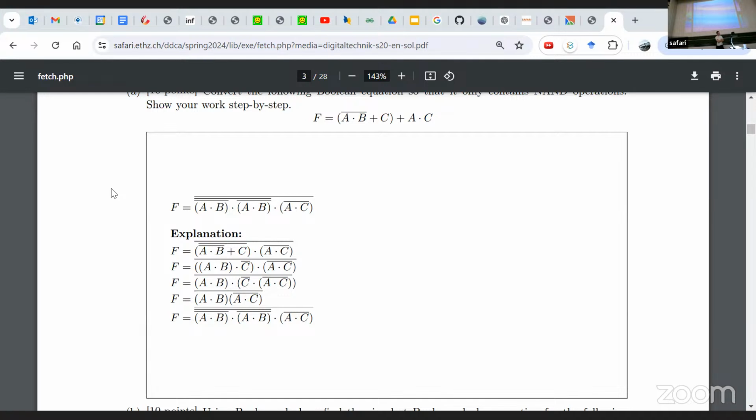In the no operation, you actually don't stop this guy from operating. You just put an operation that will not make any difference. So instead of trying to say, well, I'm not going to stop this thing, I'm just going to do something completely irrelevant. They serve the same purpose, because your purpose is that the next instruction cannot go and we need to wait.